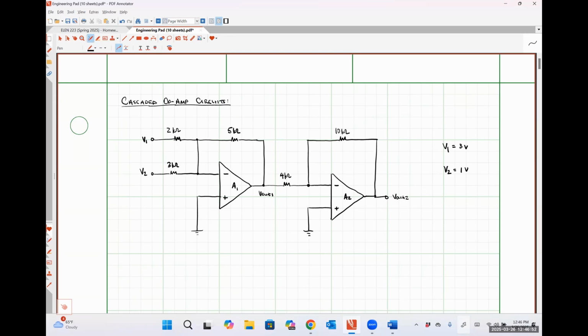So another place that you might see cascaded op-amps, and this is going to be one of either, I don't remember if it's a design project problem or if it's actually the design problem from your take-home test. I think it might be the latter, but I can just describe it to you now. Essentially, if you start out with a sinusoidal input signal, and you want to use that sinusoidal input to generate a square wave and a triangular wave, you might feed your sinusoidal input into a comparator because the output of a comparator would be a square wave.